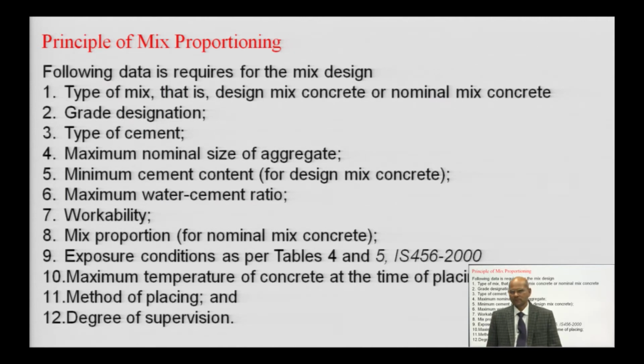We have to consider the weathering condition. Weather condition is also important. We have to decide whether it is hot weather or cold weather, and depending on that we have to plan the strategy. Then method of placing is also important, how we are going to place the concrete. Then degree of supervision is also important.